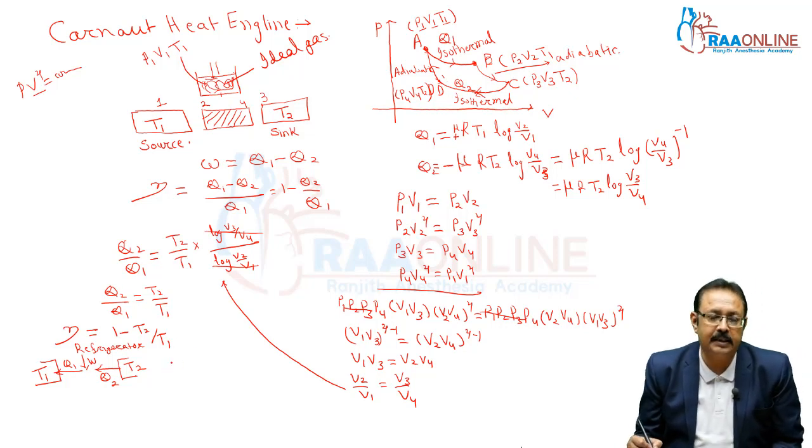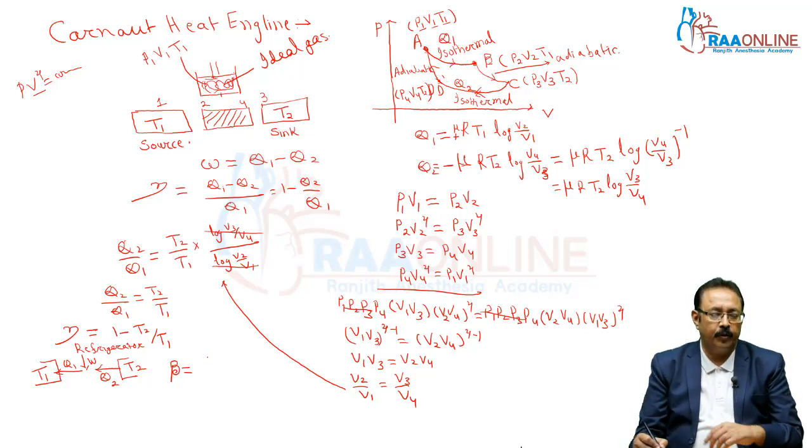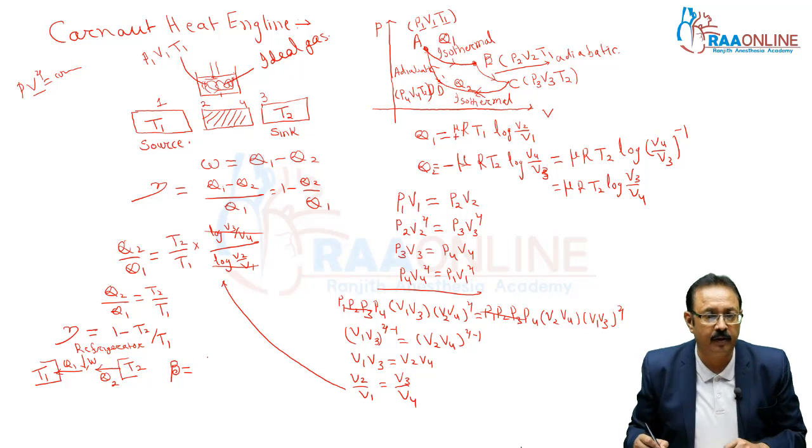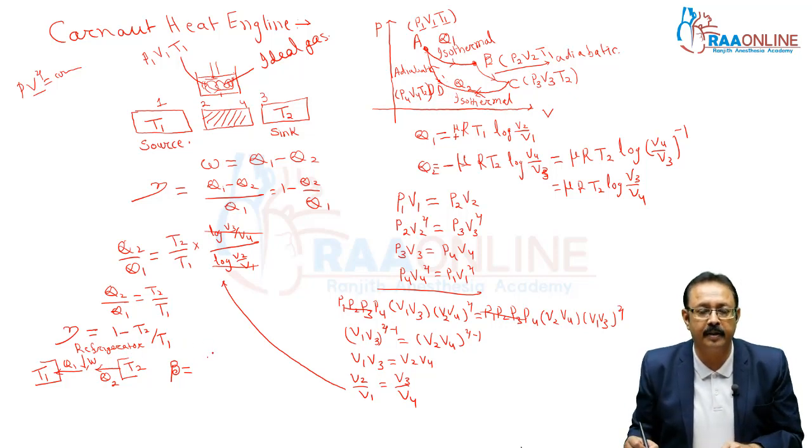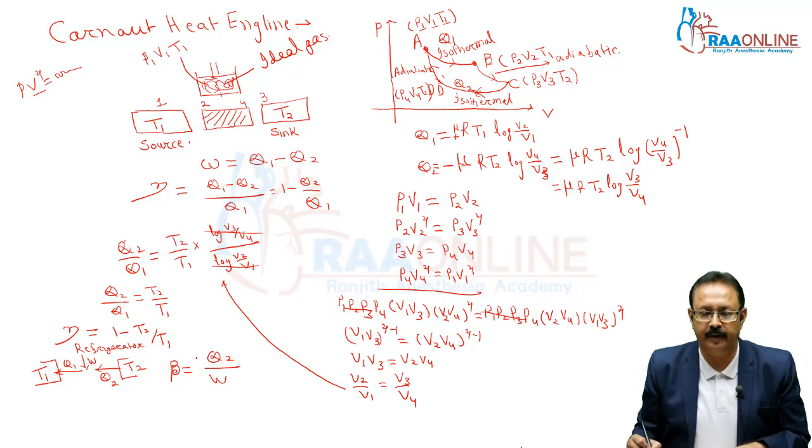But in this, we are using a term, coefficient of performance. What is the coefficient of performance? What energy you can take out from the low temperature reservoir and what minimum work you have to do on this to supply the high temperature reservoir.